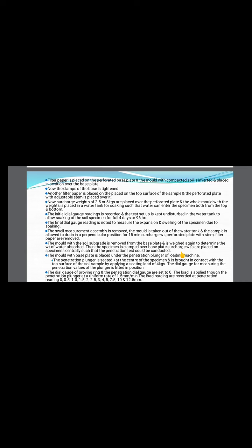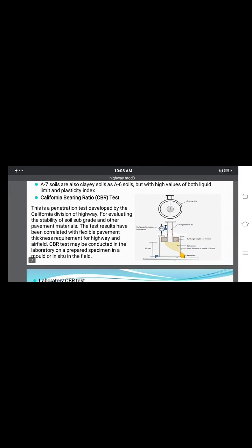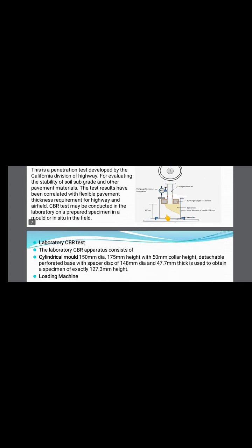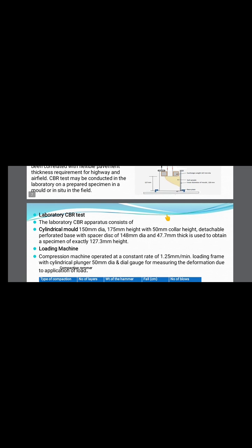And then the dial gauge has to be attached to that plate. So likewise here, see here, the soil sample you are going to collect will be here. We are going to place one perforated paper here and above this base plate, and here also we are going to place one. Then we are going to apply a surcharge weight here. Then the dial gauge has to be set to 0 and attached to the surcharge plate. Then this whole setup is placed in water for 96 hours, up to 4 days.